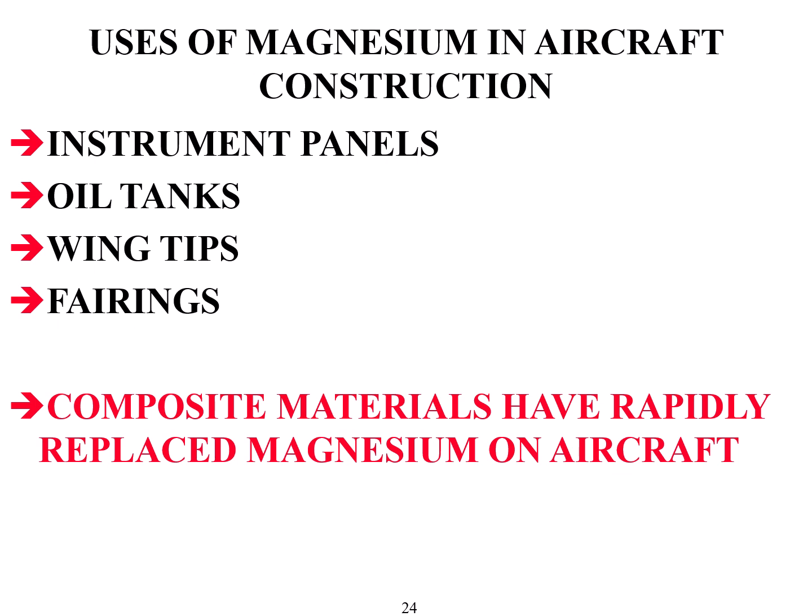That's very desirable. But as I said before, composite materials are rapidly replacing them because of the constant need to keep finishes up and continuous inspection to prevent corrosion. Corrosion acts very quickly on magnesium alloys, so your inspection intervals are increased as compared to most others. So this is one case where life in plastic can be fantastic, I guess, but I still love my metals.